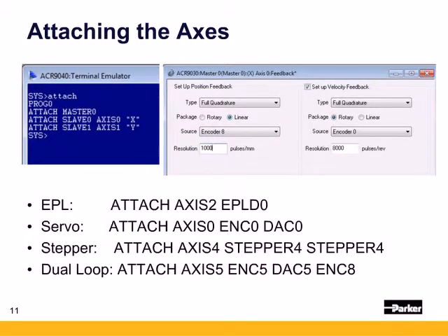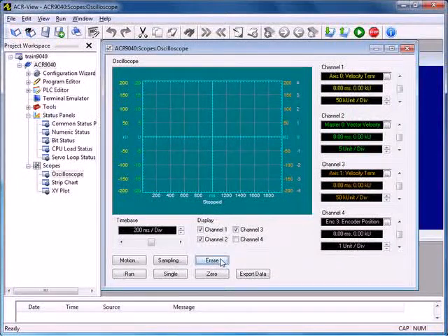A dual loop would have a secondary encoder feedback for the velocity. For Compax 3 with load-mounted feedback, both loops are closed at the Compax 3, and the axis feedback would be set to the load-mounted resolution. For line-mounted encoders connected to the Compax 3 or Aries-EPL drives, those are read back as parameters that can be used as gear or cam sources. The motor connected would be a single loop using the default feedback resolution. Master profile moves are coordinated or interpolated moves.